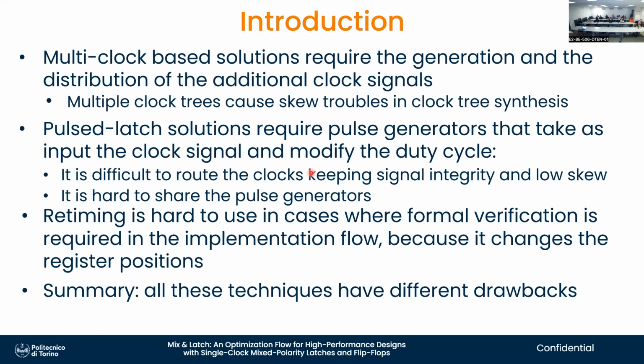So to summarize, multi-clock latch-based solutions are very nice because they provide good timing improvement by allowing time borrowing. You don't have to balance exactly the delay of every logic stage in order to achieve good performance. In a pipeline or in any flip-flop based sequential circuit, the delay of every stage, of every combinational logic block, has to be exactly the same. And that is not easy to do in practice with complex systems.